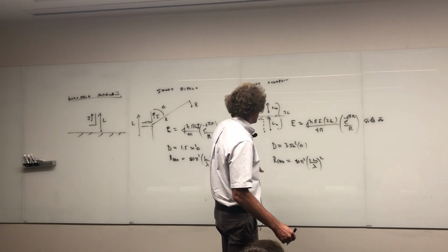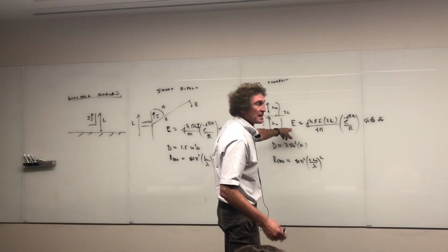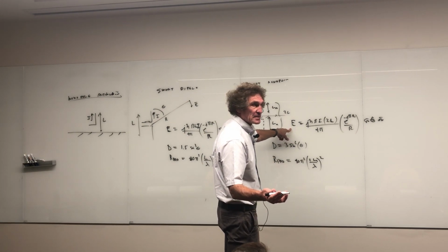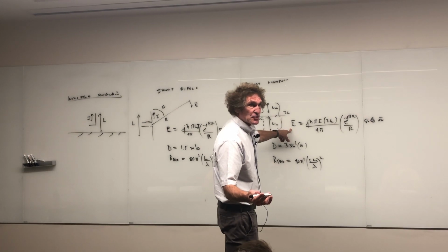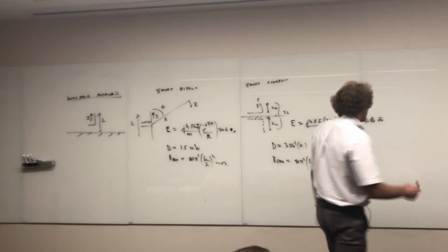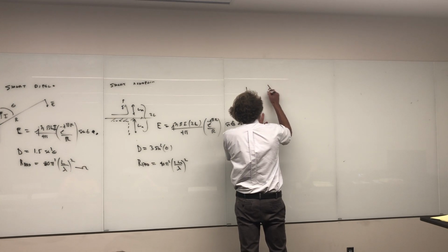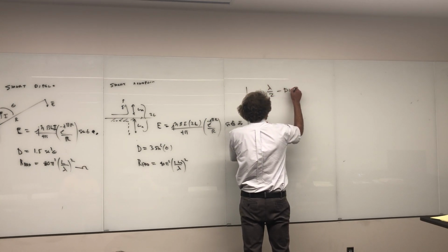All right, that's the radiation resistance. Finally, if you want the H field, you just take the E field divided by eta. That's it in magnitude. Got it? Now that's the short dipole and short monopole. If you do the half wave dipole, the only thing that changes now, we'll put lambda over 2 dipole.